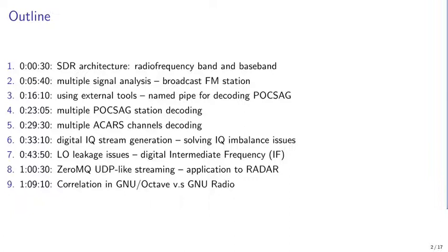We remind the basics of SDR architecture. We demonstrate multiple signal analysis on broadcast FM station and extend the demonstration to POCSAG, the pager protocol. Then we show how we can analyze multiple ACARS channels, ACARS being the protocol for communicating between aircraft and airports.